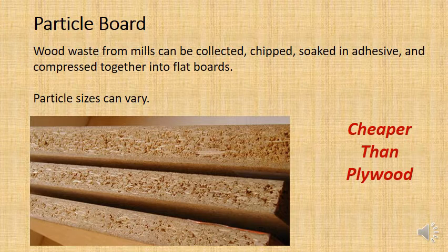Look at that particle board there. You can see it has lots of little holes all through it. Water is going to penetrate into that very easily. It's got very high porosity, a very high absorption capacity. Now, particle board can vary on the size of particles. So sometimes you have very fine particle size, where basically it's just very refined sawdust. And sometimes the particle size is very large. They're big wood chips. But either way, they're stuck together in particle board.